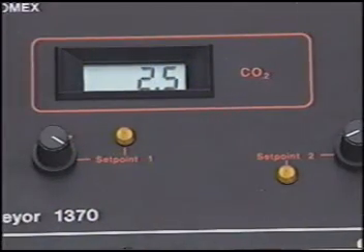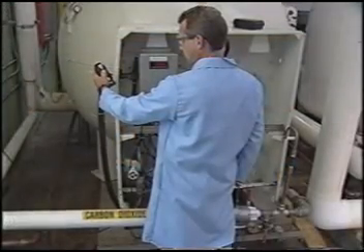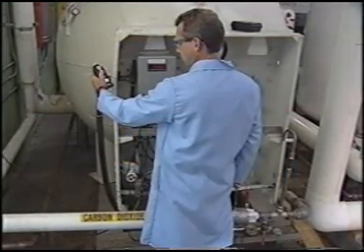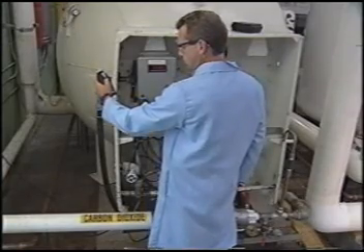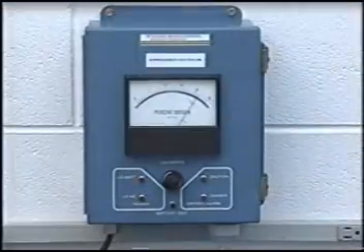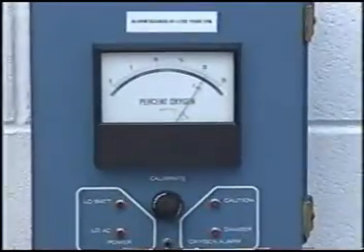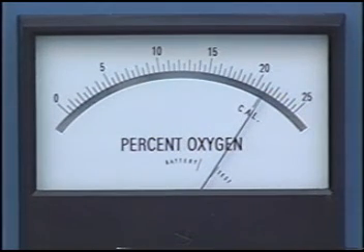To make sure the carbon dioxide level is safe, use a carbon dioxide analyzer. Take readings about 5 feet above the floor at several places and average the results. In smaller spaces that are less than 5 feet, monitor all areas. In addition to controlling carbon dioxide levels, it's also vital that you monitor the air and keep your work area well ventilated, so the oxygen level is between 19.5% and 23.5%.